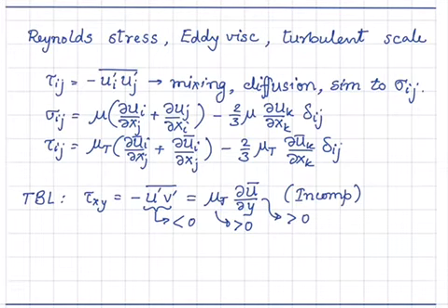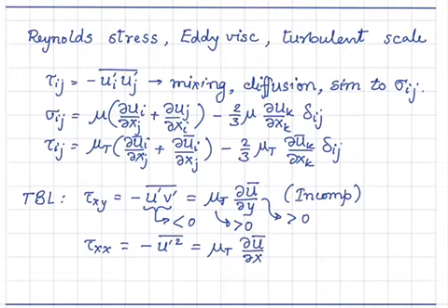So this is the basic idea on which Reynolds stress and its modeling via mu t is based. But there are other situations where this assumption does not hold. One simple case is, let's say we have tau xx, which is minus u prime square bar. This will be mu t times du bar dx. Now, in a flow, let's look at the left hand side first. u prime square is a square of a quantity. It has to always be positive.